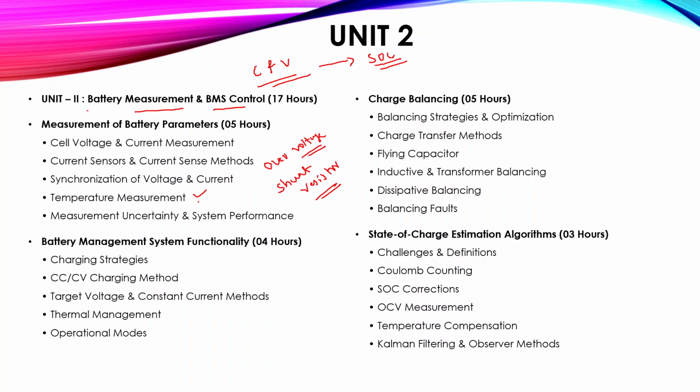As we all know, the battery has to work in different environments. We need to take care of that while designing the BMS. Measurement uncertainty directly affects the performance of SOC and SOH estimation algorithms.